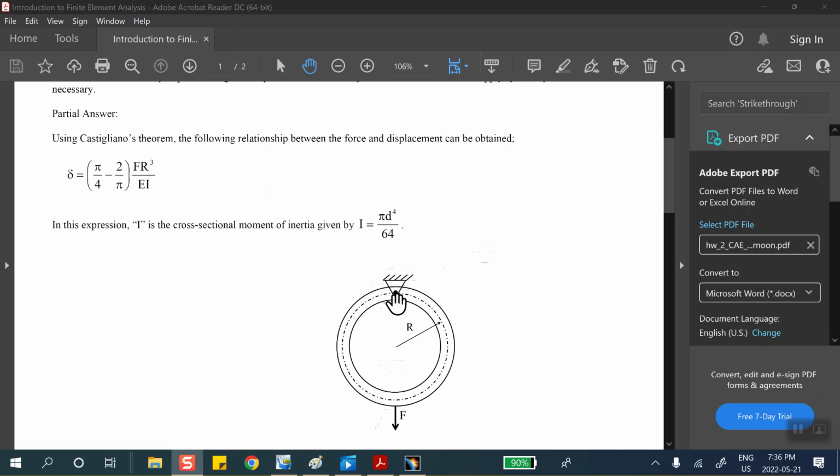You can see why, because there's nothing that makes this thing wobble to the right or to the left, and there is no force making it rotate perpendicular to that axis, and nothing that obviously makes it rotate about the third direction. No force causes it to rotate about that third direction. This being the case, three translations being zero here and three rotations being zero here